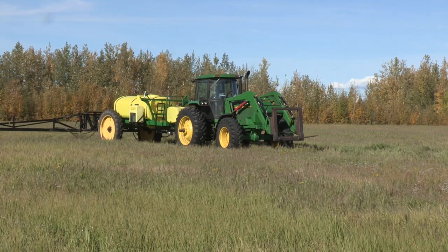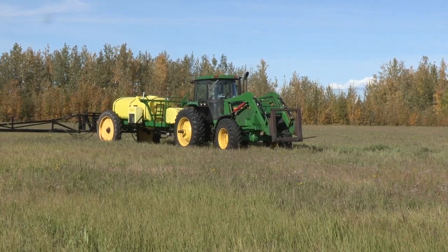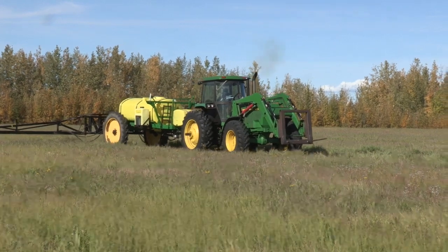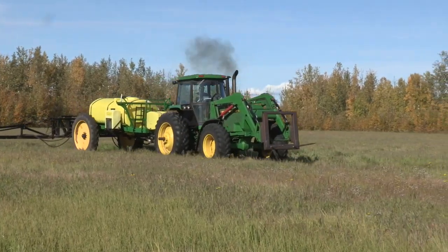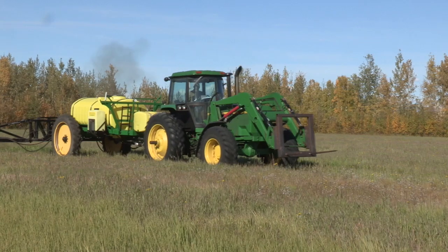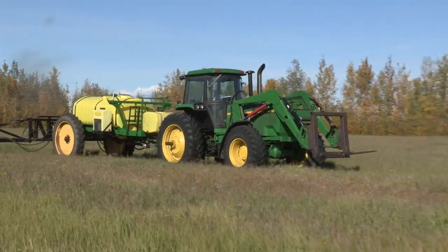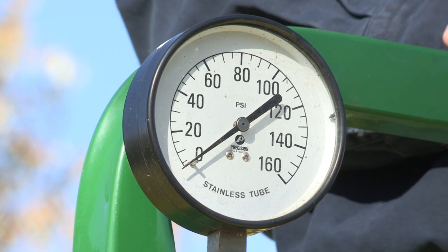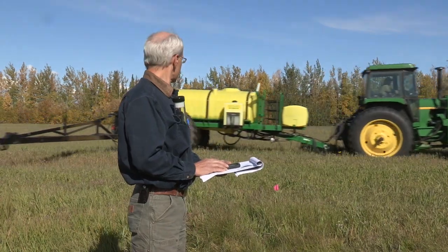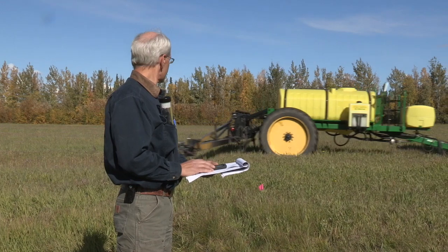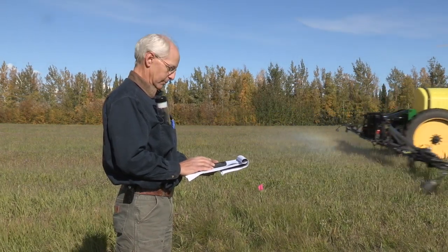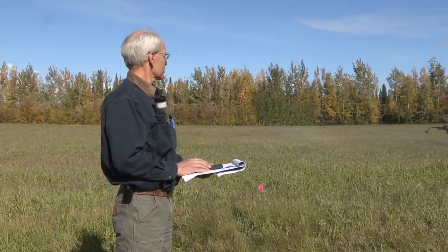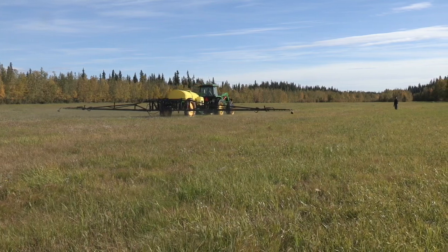First, you'll need to determine what a comfortable or suitable travel speed is based on your field's conditions. Have your sprayer tank filled approximately half full of water to simulate an average condition. Next, set a pressure for your sprayer. Then, measure out a 204-foot long test course and mark it with flags. Run at your determined speed between the flags and time how long it takes.